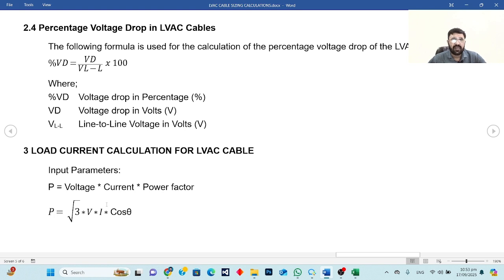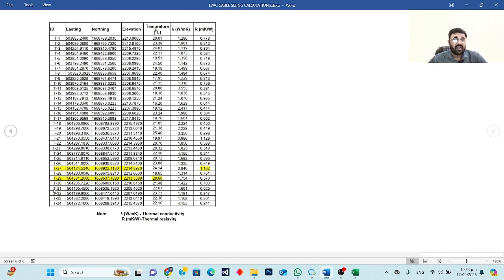So that's why we calculate or check its maximum output current, at what temperature we are using. These are the values we get from the geotech report from the soil testing, how much is the maximum temperature. Like in the previous one, I have some values, you can check that 28.6 is the maximum, so that's why we take it as 30 degrees centigrade.